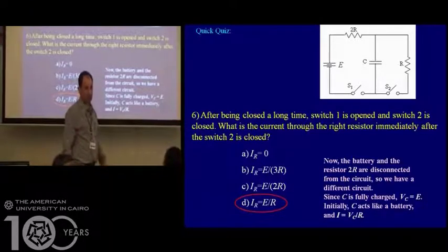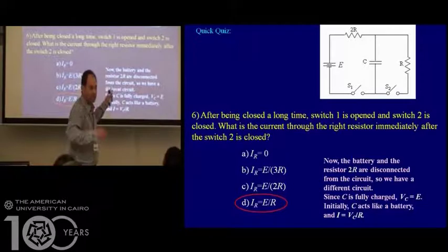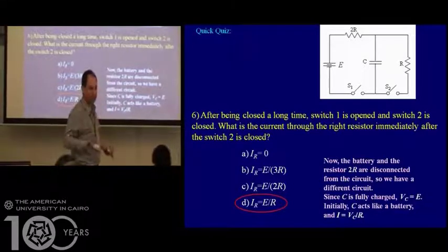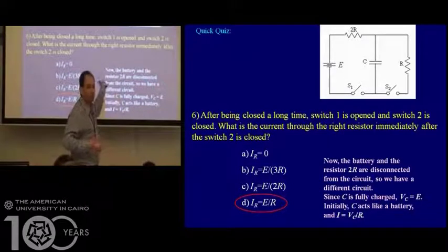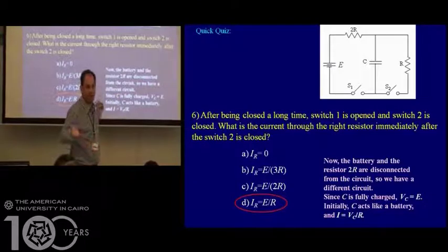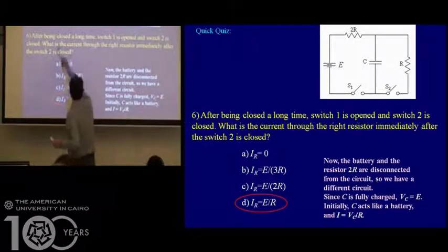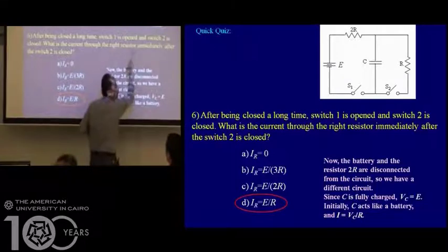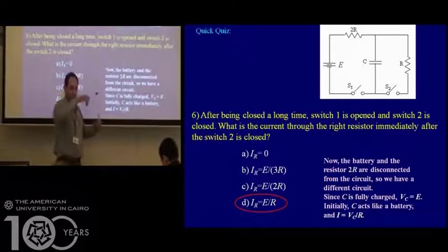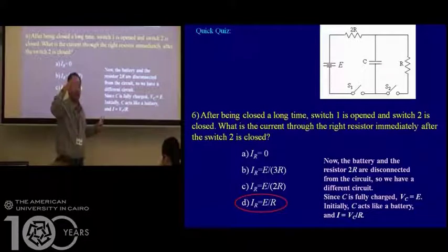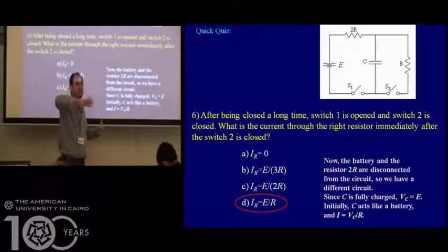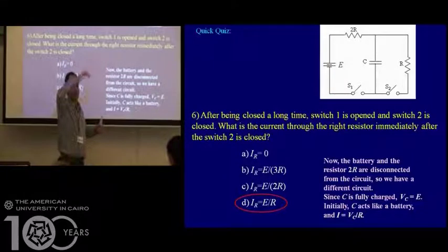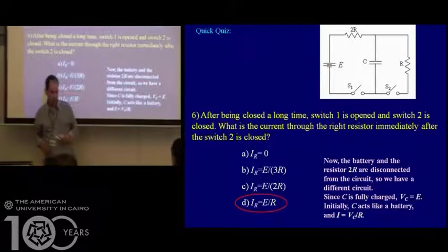If there is no charge on the capacitor, then it doesn't matter what you do with S2, nothing is going to happen. That's why I said after being closed for a long time, switch 1 is open. After you close switch 1 for a long time, then you make sure that you have charged the capacitor already. Now you open it and switch 2 goes on.